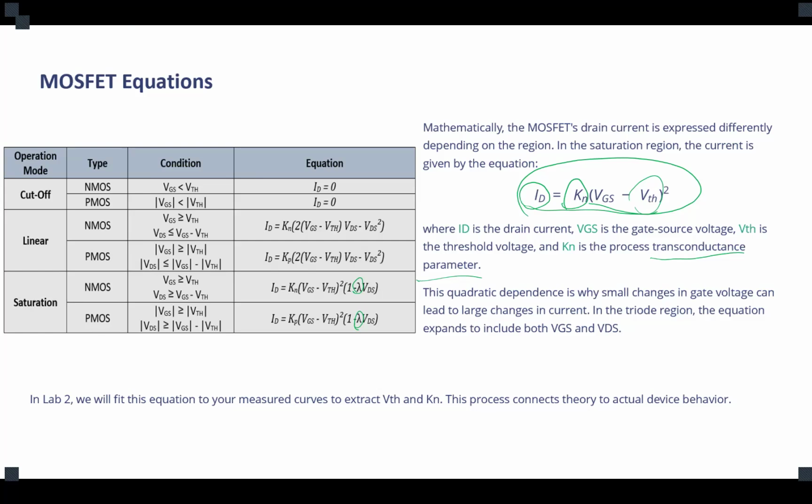Now, remember, if you want to do that, you should not use the MOSFET without a resistor connected in series with the drain. So you have to basically limit the current so you won't burn out your MOSFET. Is that clear? So we always use the semiconductors in series with a certain current limiting resistor. Very good.